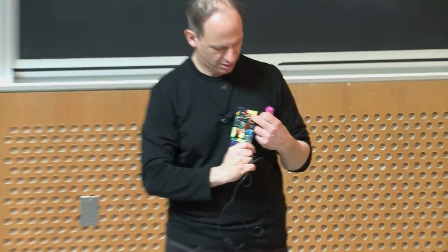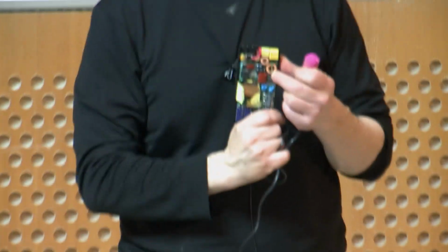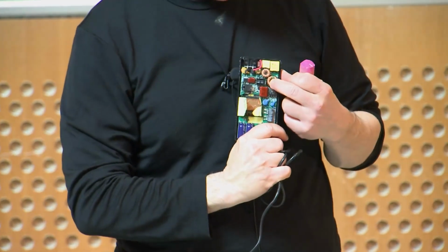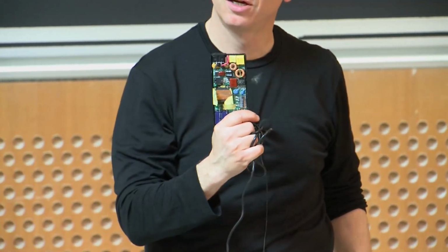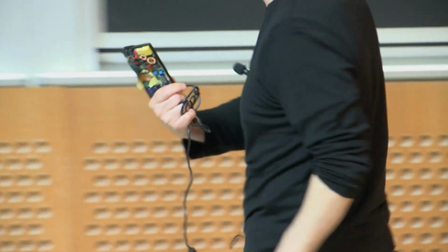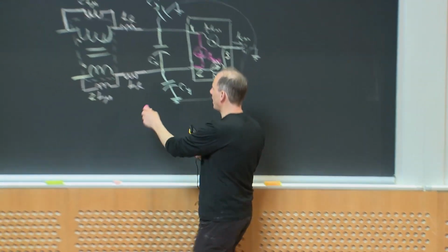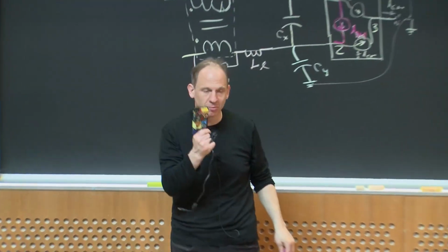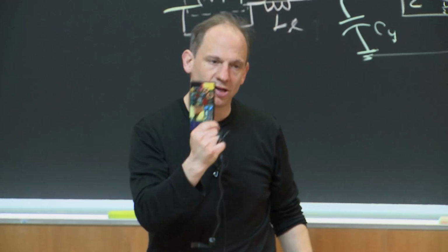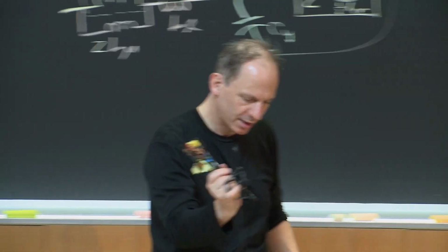These are common mode chokes right here. Okay. And actually what you'll see is the two sets of windings are identical and they're split up on the core. They're split up on the core actually to help enhance the amount of leakage inductance that we have from those things. But it's symmetric and ungapped cores. Okay, and that's very convenient.